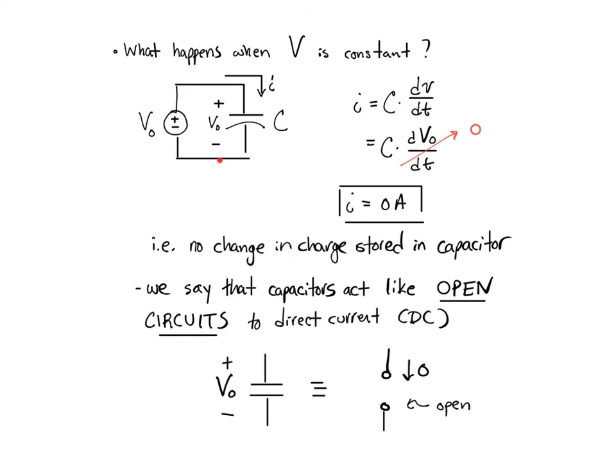So in this case, we're going to take a capacitor. Note that I drew the symbol a little bit differently in this case. I have a flat line for the top plate and a curved line for the bottom plate. This is the same thing. It's just a capacitor, but the curved plate implies that it has to be the lower polarity. So we're implying that this is the negative side of the capacitor. It has to do with the type of capacitor utilized. Certain capacitors, and the way they were manufactured, have to have the polarity set up a certain way, otherwise you could damage the insulator. You still treat those the same way, you just note that this dictates how you have to wire the capacitor up.